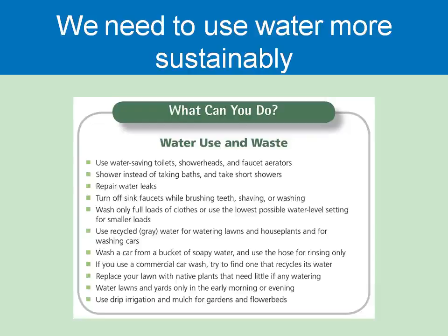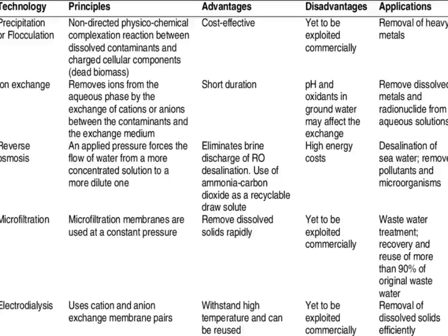Some of these achievements are ammonia removal from the wastewater of industry. Here an ion exchange technique using a weak acid cation exchanger based on methacrylic acid is employed to remove ammonia from wastewater in the form of ammonium sulfate, which can be reused for the manufacture of fertilizers. The process has good application potential not only for pollution abatement but also for the recovery of the pollutant in the form of useful salt.